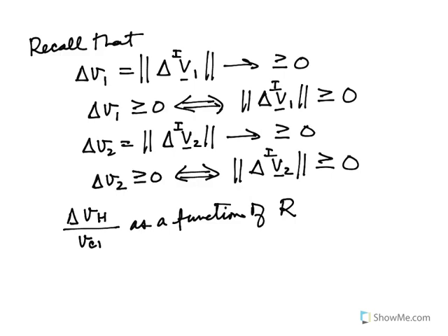Once we did that, we focused on coplanar orbital transfers, where the initial orbit, the final orbit, and the transfer orbit are all in the same plane. Then we focused on two impulse transfers, which led us into the discussion that was the basis of this lecture, the Hohmann transfer. The Hohmann transfer gives us a two impulse transfer where both impulses are applied tangentially, one at the initial orbit, one at the final orbit.